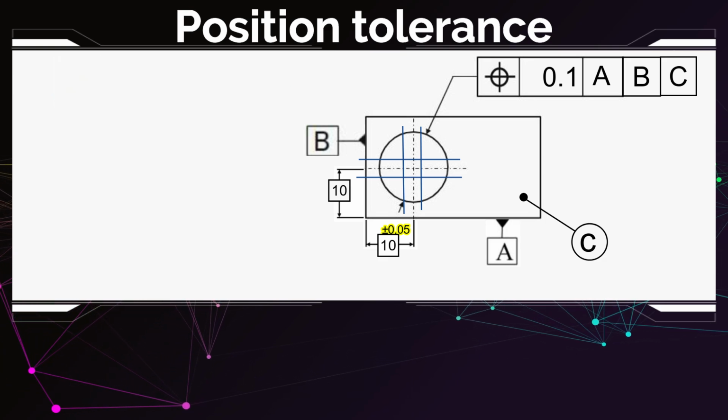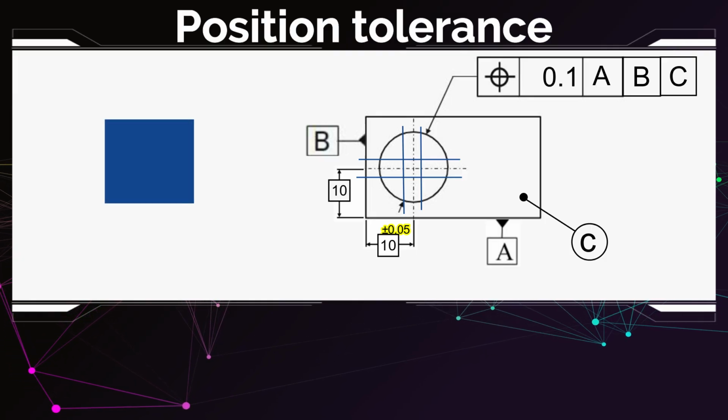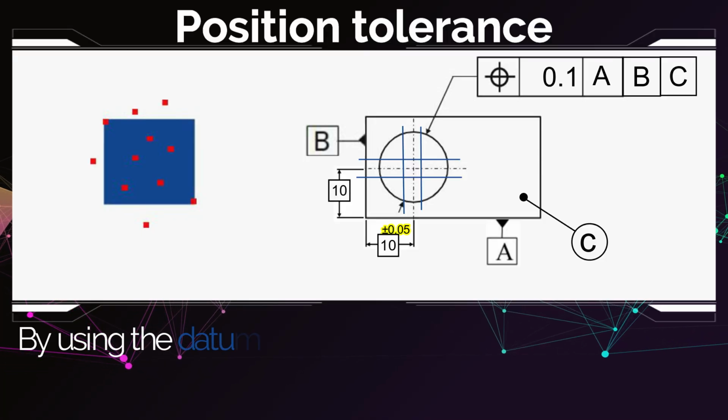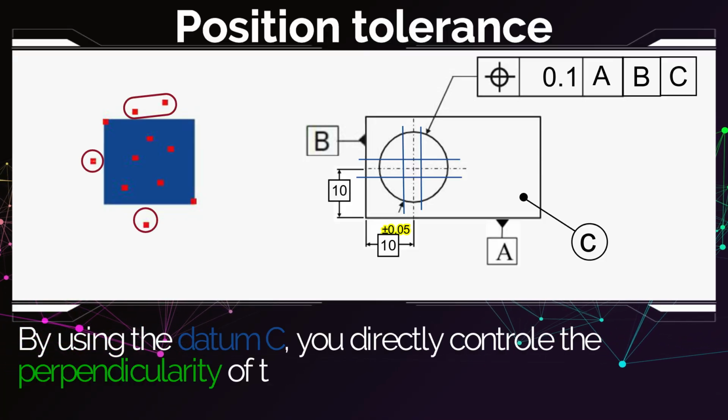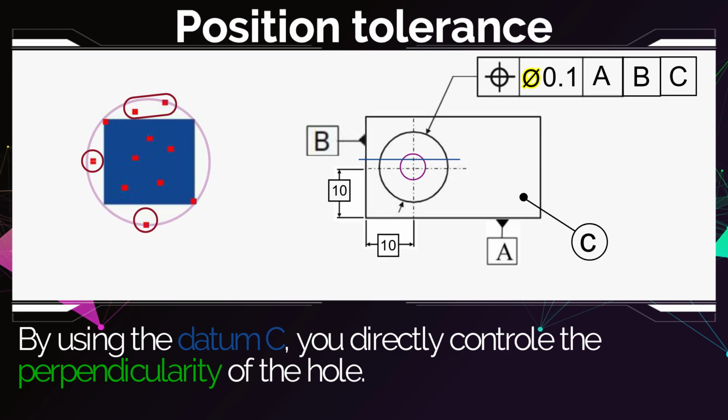If you look at the tolerance zone without using the diameter sign, it'll look like this. And your measurements will lie like that. All these points are not accepted, but once you use the diameter modifier, you actually increase the tolerance zone without any negative effect on the function. You transformed your tolerance zone to a circle with a diameter of 0.141, which looks like that.